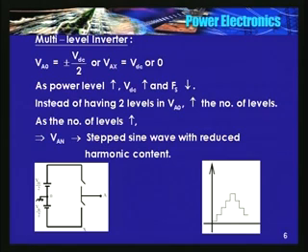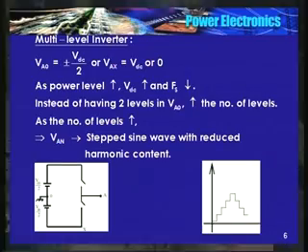So if this voltage itself is changing, the maximum voltage that this switch should block also increases. So in other words, as the DC link voltage increases, the stress on the inverter device also increases. So you cannot allow the DC link to increase above a rated value. How do you do this?